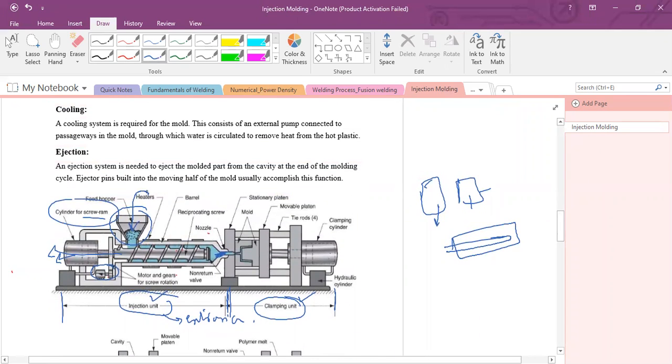The pellets and granules are normally fed into the barrel from the hopper, and in the compression section this raw material will melt, and the screw will rotate and generate pressure and frictional force. Along with the pressure, the material will compress and move in the forward direction. In the pumping section, the material pressure is normally high, because the screw is continuously rotating and producing pressure.